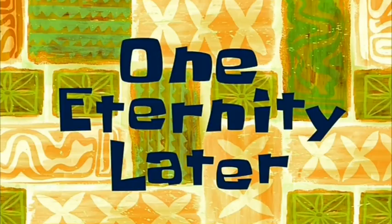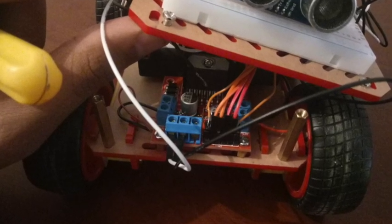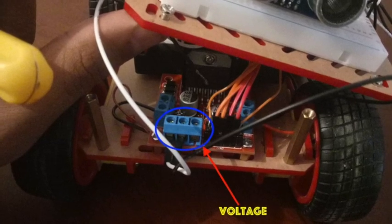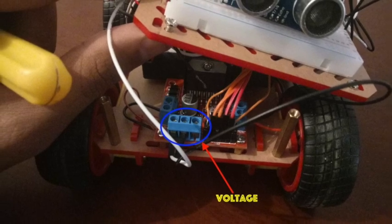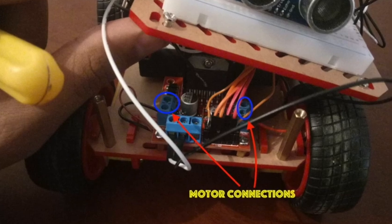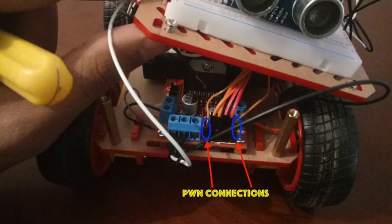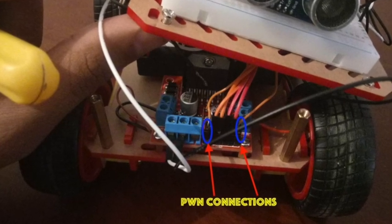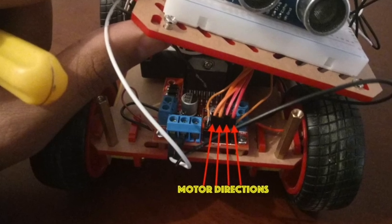One eternity later. Hi, my name is George. I was the one responsible for connecting the H-bridge to the motors. First, I connected the voltage, ground and source to the bridge, and then I connected the motors to the side as shown. Then I connected the PWM ports to the Arduino through this port and the direction ports through these ports.